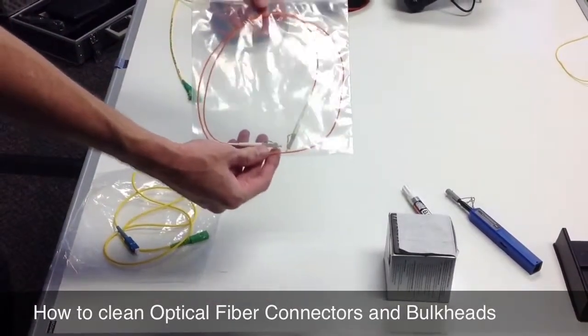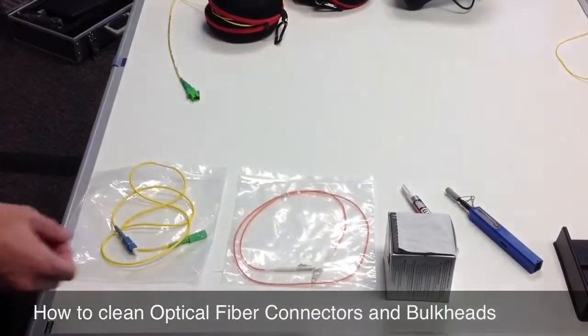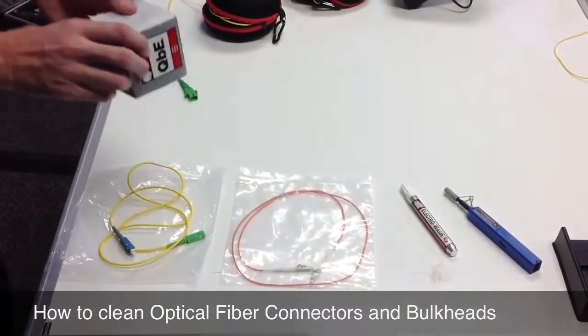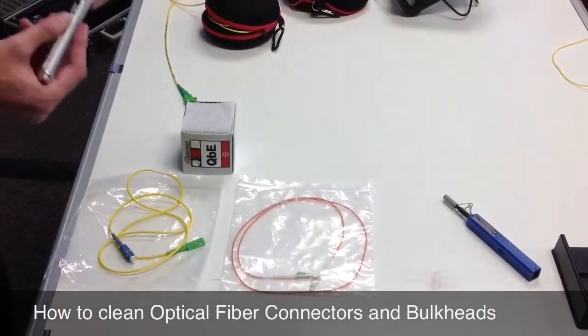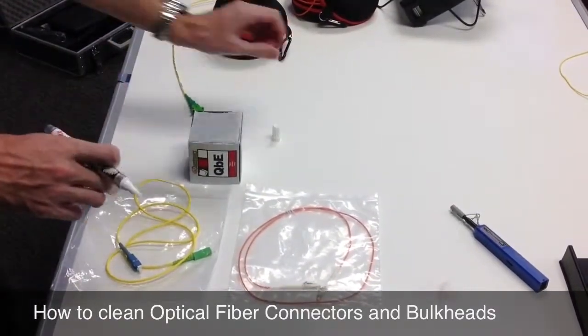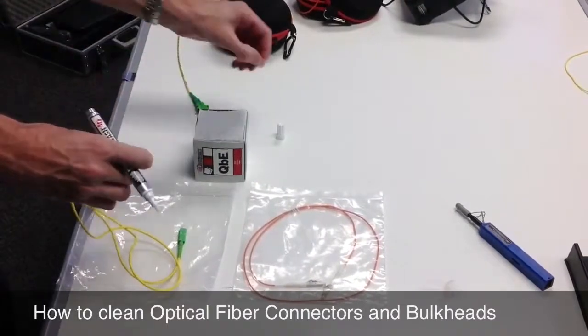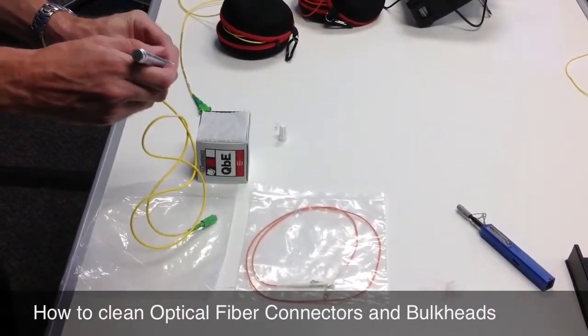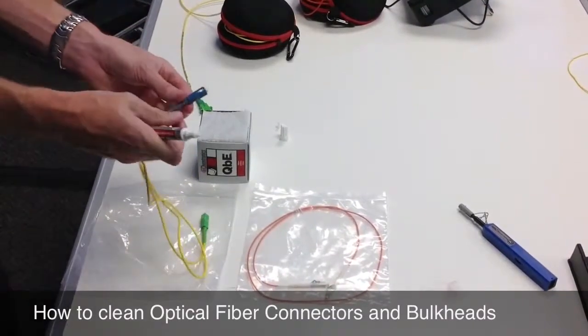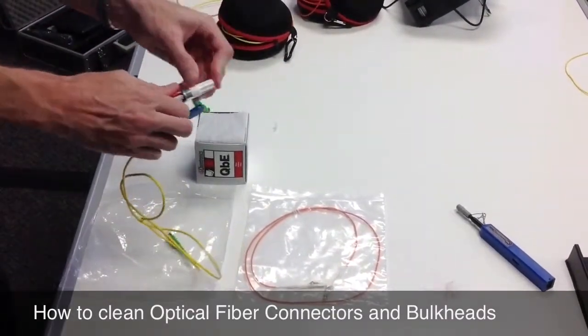Now we will step through properly cleaning a connector. You can either use a dry wipe, shown here, or use a wet cleaning solution. For the dirtiest connectors, we recommend first using the wet cleaning solution, followed by the dry wipe.